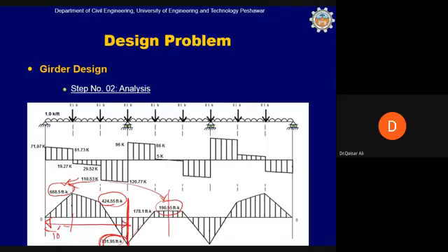This negative bending moment and this negative bending moment are one and the same. So if you design for this negative bending, automatically you design this part, and then this positive bending moment, and these three positive bending moments, we will adjust in the reinforcement, according to this equation. So you start doing this. I will.